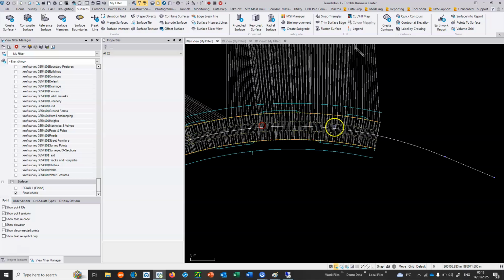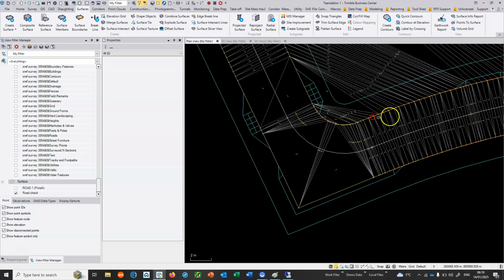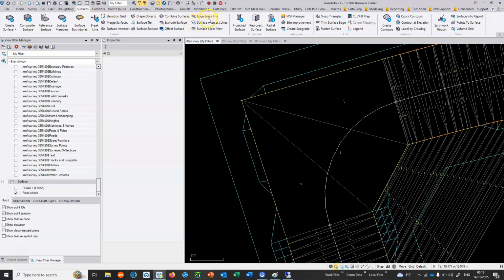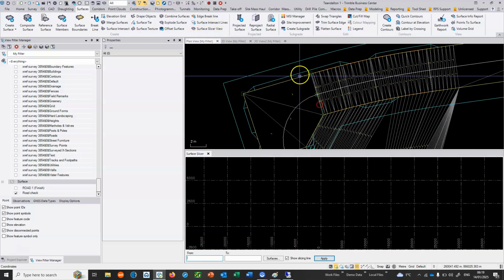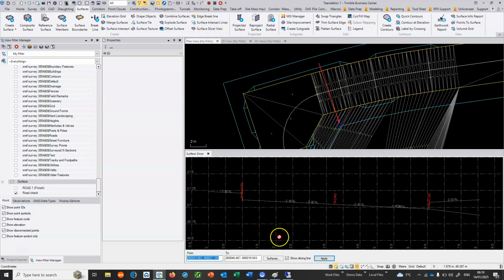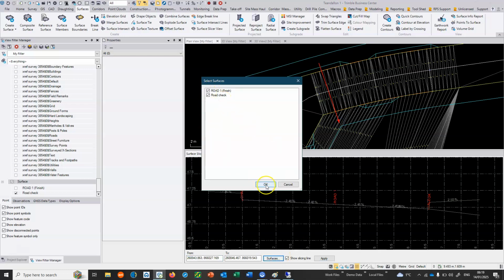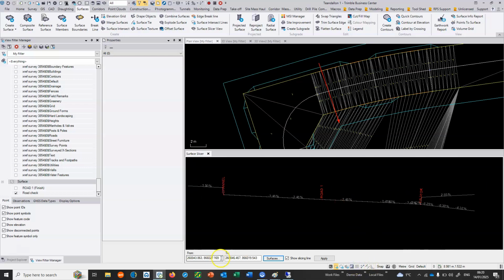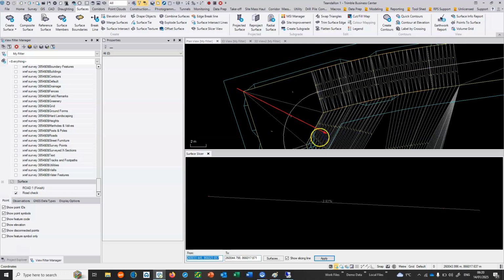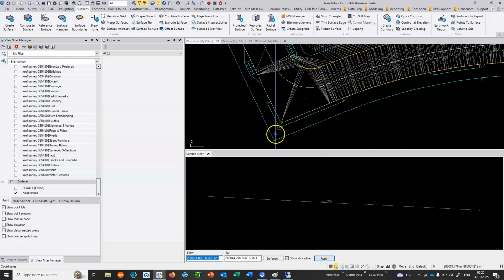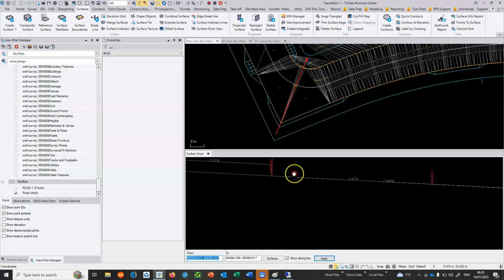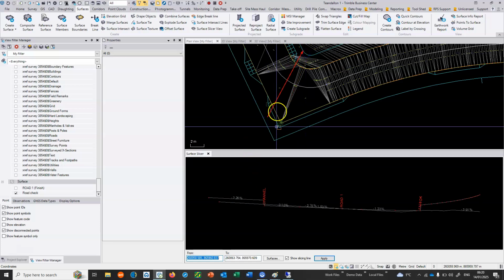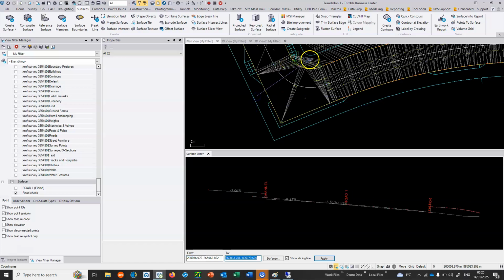What we can also do here is probably turn the gullies on, or the gully layers on, and check it there. Very useful one to use as well is obviously the surface slicer view. And we can just slice our way through. Just make sure that we've got the right surface. So we've actually got both surfaces on there. So we're just checking that there's nothing untoward between both surfaces. If we go down here, we'll see a very dramatic difference probably between the surfaces. It's actually handled that one not too bad, but we can see there's differences here, that's for sure.